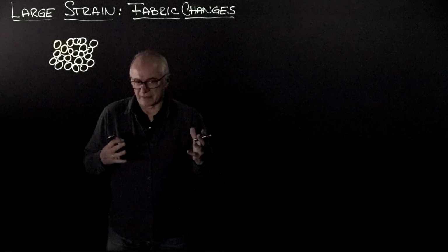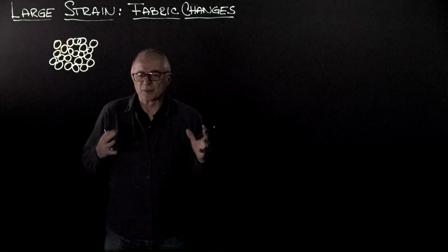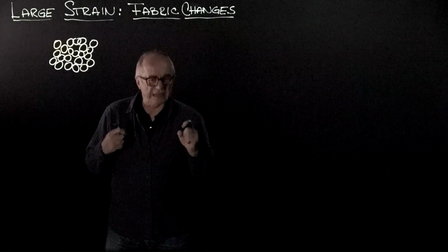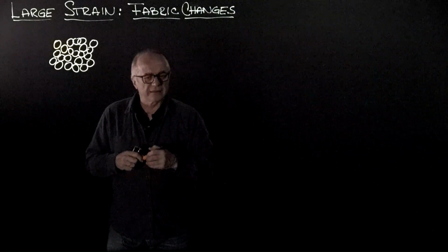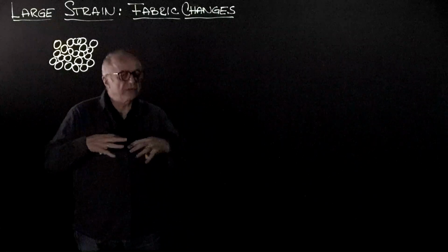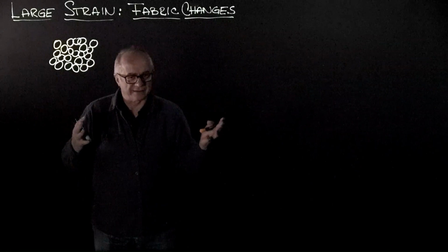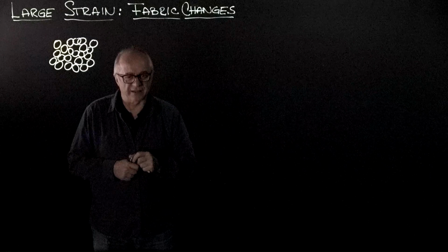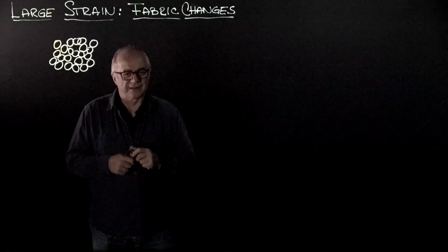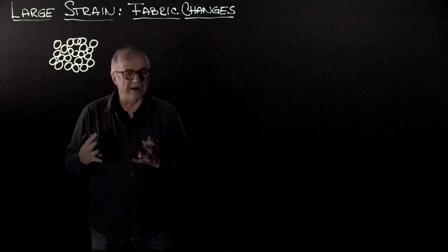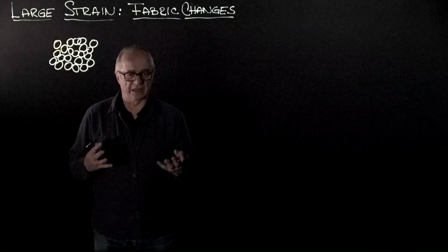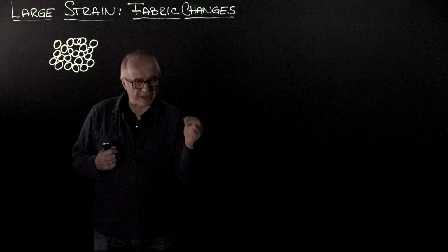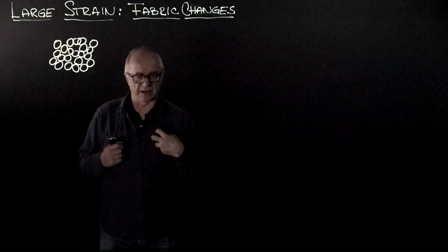Discrete element methods give us a wonderful opportunity to understand the behavior of soils at the particle level. In my mind, the key goal is not to simulate the whole soil mass underneath a foundation. For me, a key part of discrete element modeling is to understand soil behavior at the particle level, to feel as a particle.